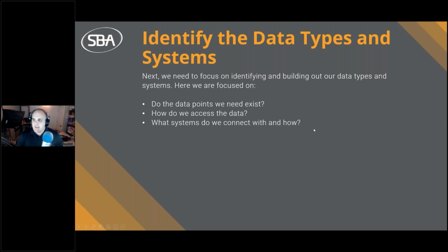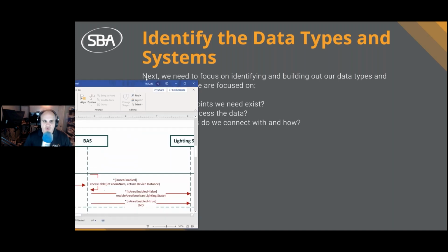So normally, if you're doing like a chiller integration or something, I would just type in the chiller's BACnet interface card or LAN card model, and I would look up the data types, and I would say, okay, these are BACnet AVs, so that means that they're writable, so I can use those points, or they're BACnet AIs, that means they're not writable, so I can't use those points. However, when you get to more complex integrations, and give me a second here to bring this up, you're going to have to start to build out some actual integration deliverables.